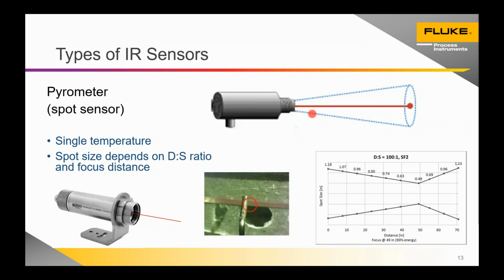When we go down to lower cost sensors, this is a mid-price sensor, we typically go up to 70 to 1, and that's because we've got smaller optics and a smaller body, and the units that are 2 to 1 are really tiny, you know, the size of your thumb. They've got a small lens and they're very short.